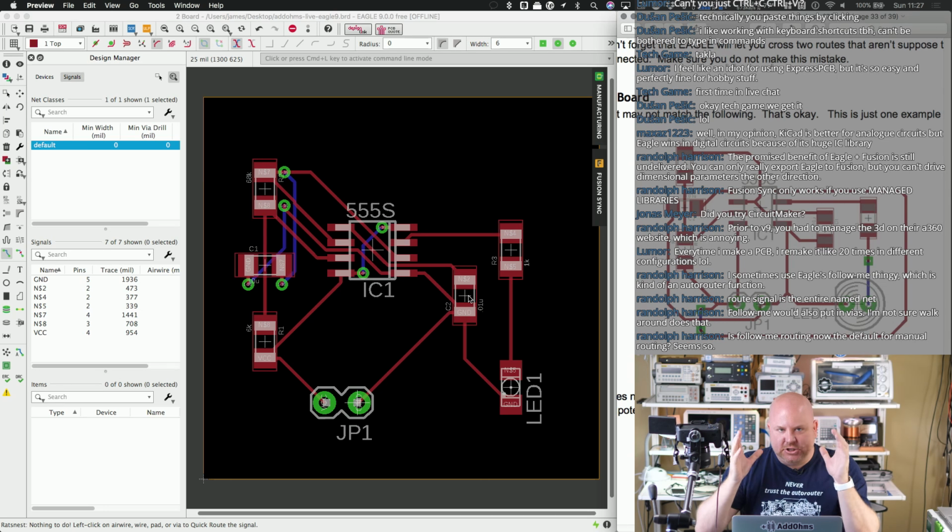And so whatever the component's on will put some pressure on the underside of it. And so in general, I try to avoid vias directly underneath a component just so that there's no issues when it gets soldered. Again, if it's a high quality PCB process or you're hand soldering, it's not as big of a deal, but it's just something to try to avoid. Also from a debug perspective, vias are really nice because you can actually scrape away the solder mask and use them as test points.